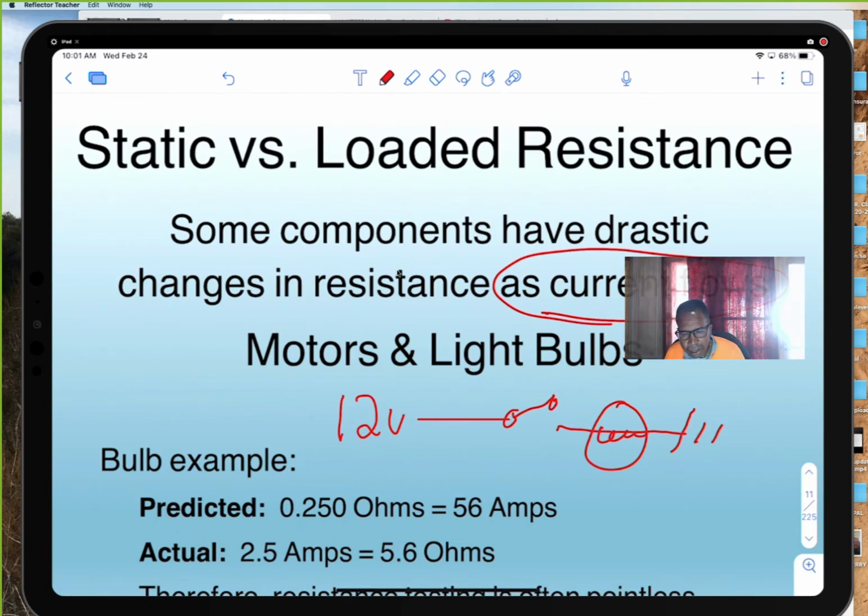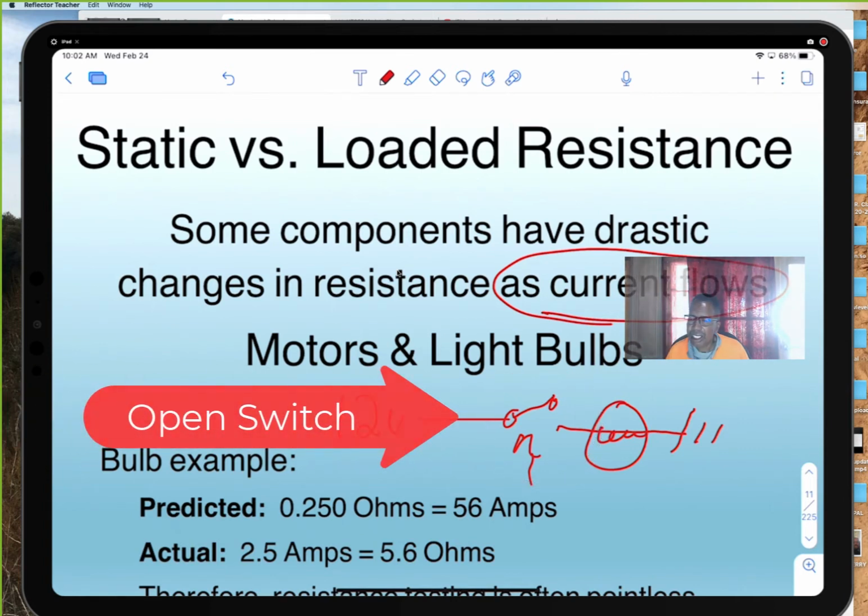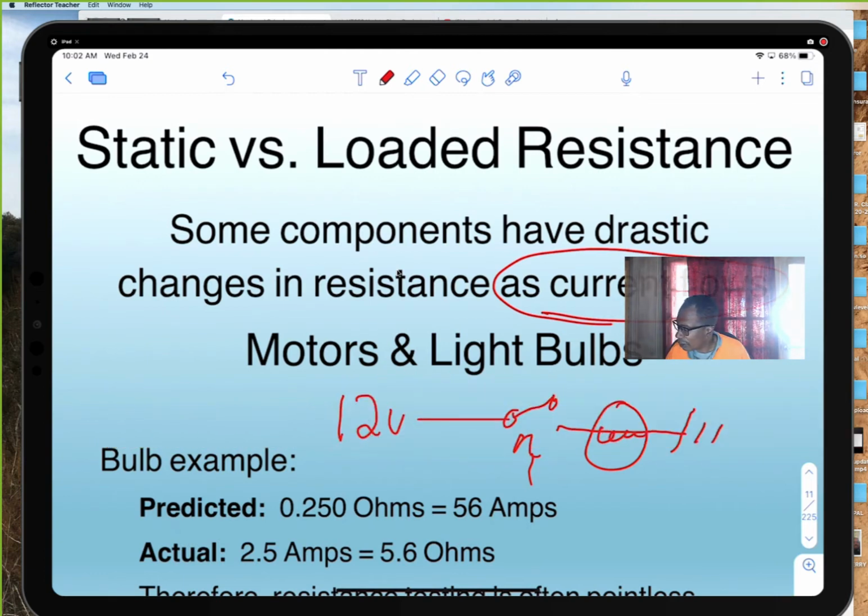Now, obviously, if this switch is in what position? Mr. Garcia, you just said it, right? This switch in what position? Open circuit, right? And like Mr. Hernandez just said earlier, it has to be a complete circuit. Current has to flow in a complete circuit. I got to see a difference in pressure. For current to flow, it needs to see a difference in the pressure, a pressure differential. When it's open, there's no current flow. Yes, exactly. When it's open, there's no current flow. I just have potential voltage. All I have right now is potential.